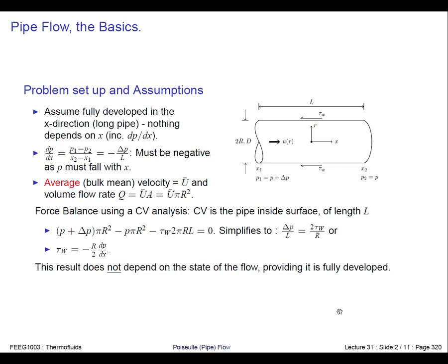Okay, so what we're going to take is a round pipe. It's very long, and we're going to assume it's fully developed. What that means is nothing is changing in the flow direction except the pressure. And more specifically, the pressure is changing linearly.